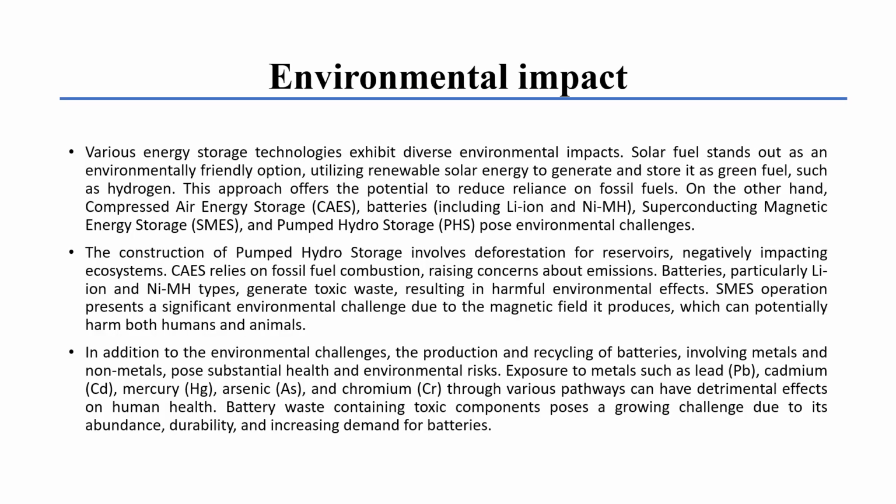Environmental impact. Various energy storage technologies exhibit diverse environmental impact. Solar fuel stands out as an environment-friendly option, utilizing renewable solar energy to generate and store green fuel such as hydrogen. These approaches offer the potential to reduce reliance on fossil fuel. On the other hand, compressed air energy storage, battery, superconducting magnetic storage and pump hydro storage pose environmental challenges. The construction of pump hydro storage involves deforestation for the reservoir, negatively impacting the ecosystem. And compressed air energy relies on fossil fuel combustion, raising concern about emission.